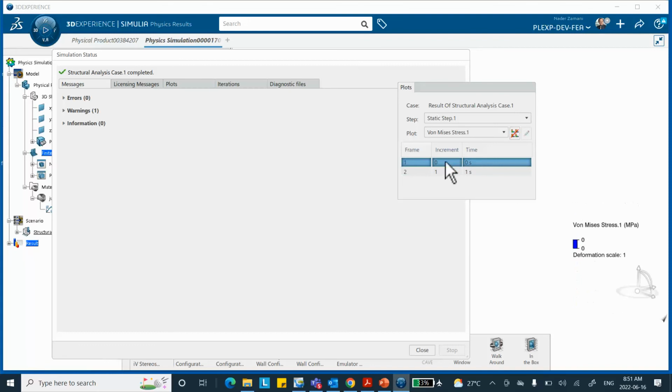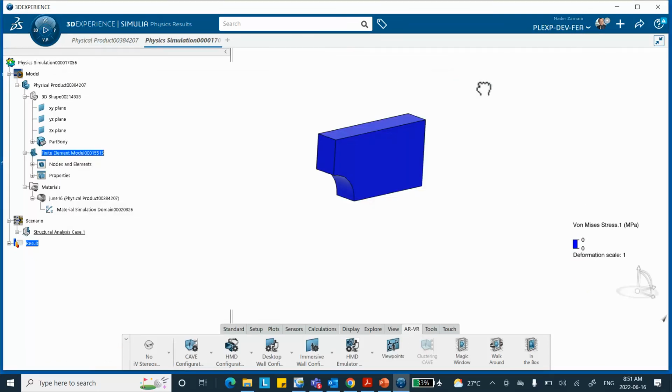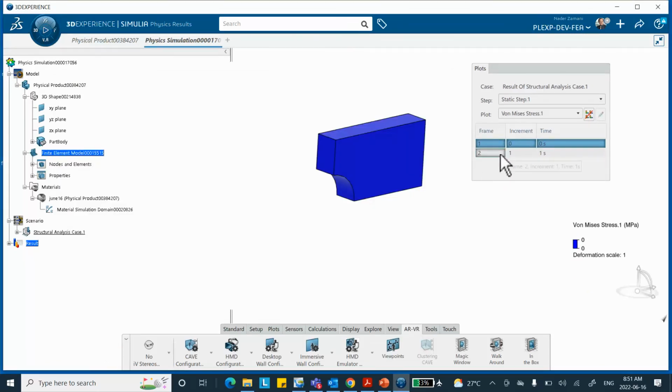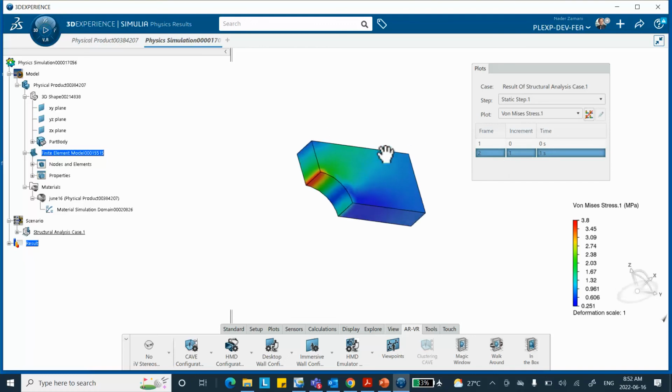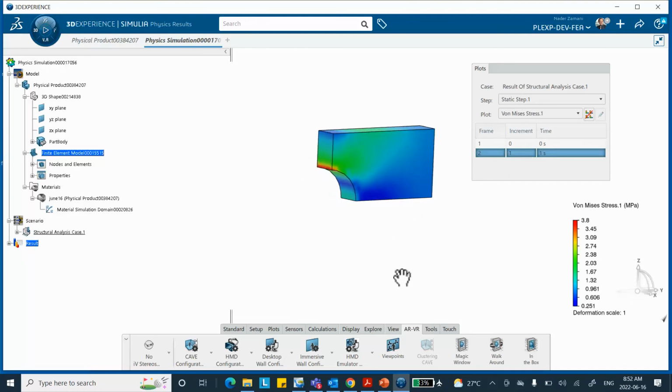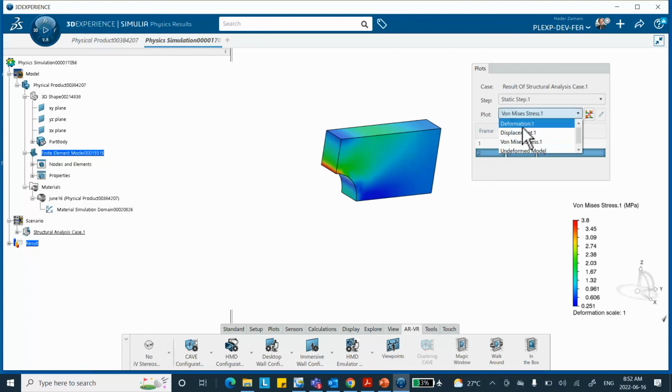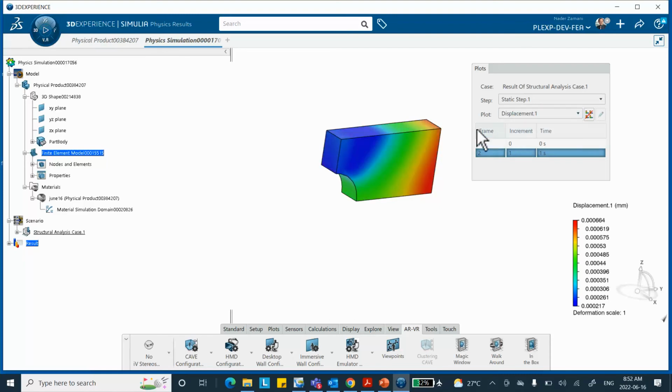This is basically before the load is applied. Everything is zero. This is after the full load is applied. The biggest stress is at the bottom. You expect bottom is here, okay, etc. And then you can do displacements and generate stuff that is not easy to do in Catia. In Catia, if you want some stuff generated, it's not automatic. You have to create Excel files, import it, do the graphics, plotting, and things like that in Excel. Here's the deflection, the biggest deflection at the end because you're pulling it on both sides.